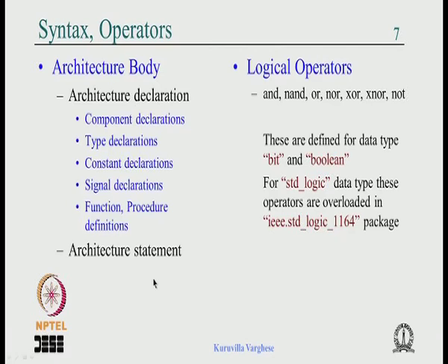So let us turn to the logical operators. You have all the logical operators: AND, NAND, OR, NOR, XOR, XNOR and NOT. But the trouble with VHDL is that the basic operators support only bit and boolean. As we described in the first slide, we are not going to use bit because it is restricted to 1 and 0.